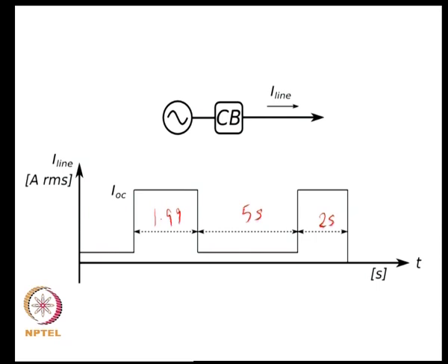Again, this analysis of assuming constant trip rates and reset rates is a simplified analysis. Okay. So, if you look at what we are doing, we are trying to look at the implications of adding a distributed generator to a distribution system, rather than doing a precise analysis on how to set protection levels.